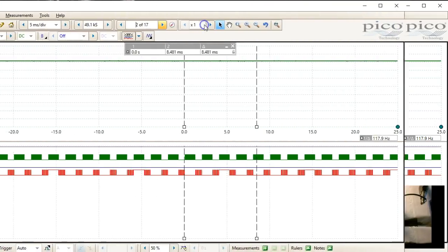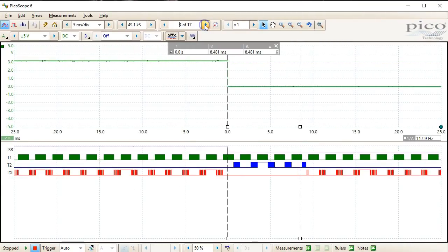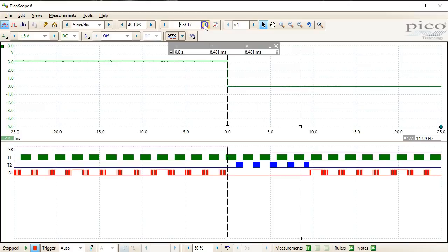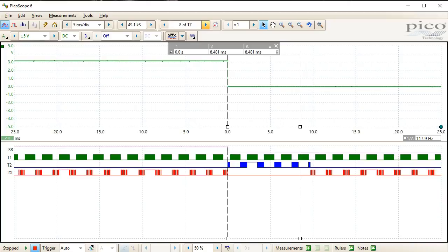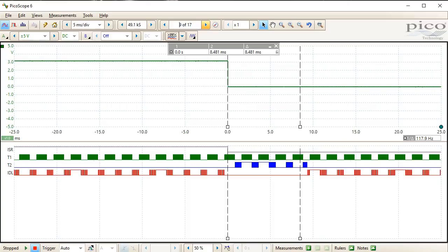As you go through the collected traces, you can see that most of the time, pressing of the button caused the ISR to go low, and the blue LED started to toggle for about 8.5 milliseconds, give or take a few milliseconds for preemption. When the button press came while the Blinky1 thread was not running, the Blinky2 thread started to toggle the blue LED immediately. However, when the button press happened while Blinky1 was running, the Blinky2 thread had to wait until Blinky1 voluntarily blocked.